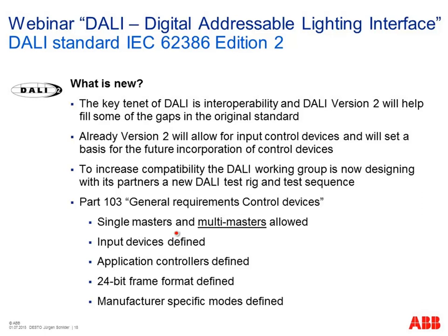And DALI 2 will also allow a multi-master concept, so more components which can actively send commands by themselves to other components. And the slaves behind are typically the electronic ballasts, which are operating the lights. So it will be possible to add maybe a presence detector, or not only one or two presence detectors, any additional touch panels, and many of them into one standalone DALI system. So that's completely new. Besides these 64 slaves we can integrate in one DALI system, up to 64 masters will be allowed in future.